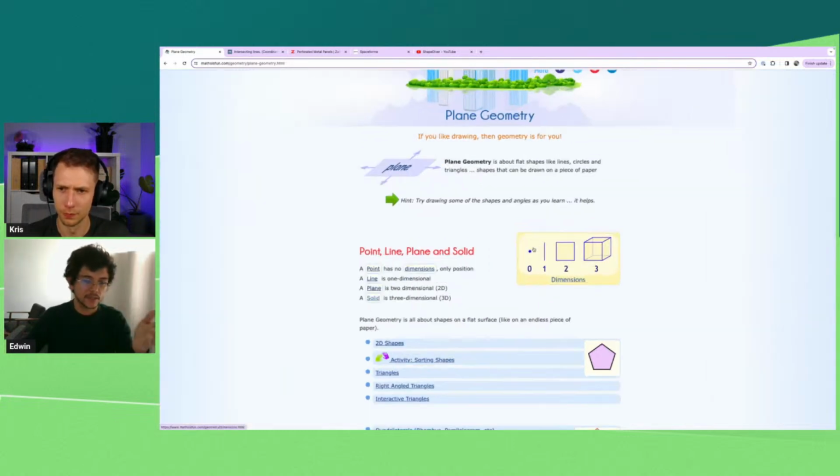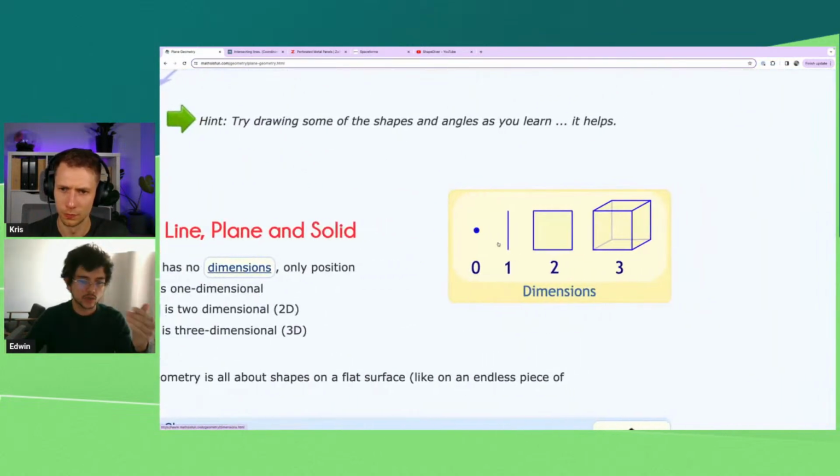Of course, the simpler the geometry, the faster it will go. That's why I always use point containments, lines, intersections, polylines. So the simpler your geometry, the faster it will compute. And at the end of the day, every very complex geometry is composed of small, very simple pieces of geometry. So you can always decompose anything into simpler pieces of geometry on which you can then operate.